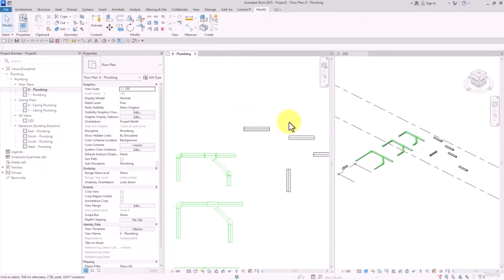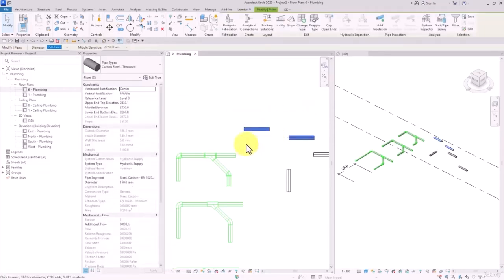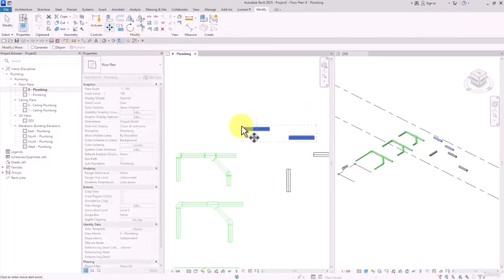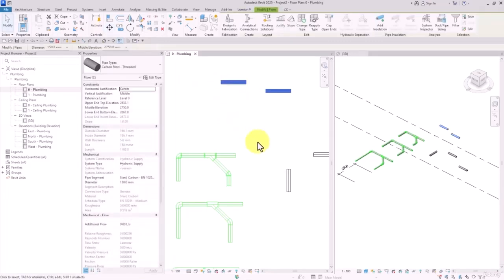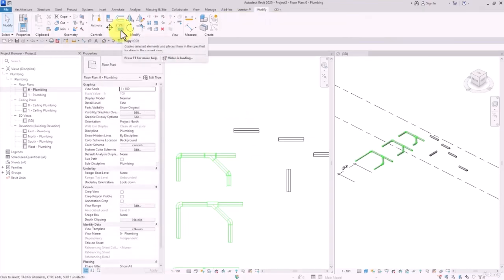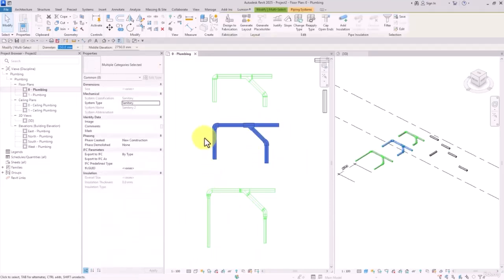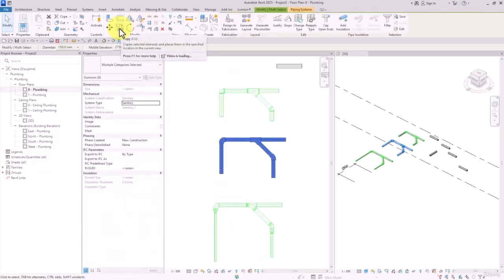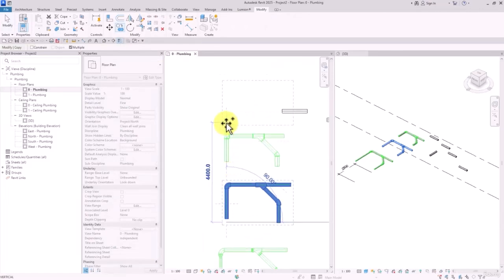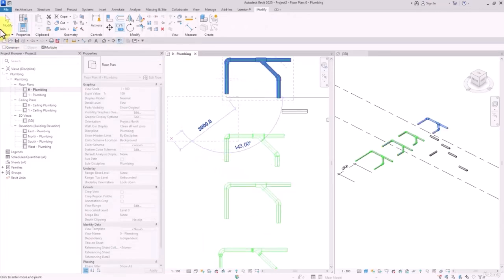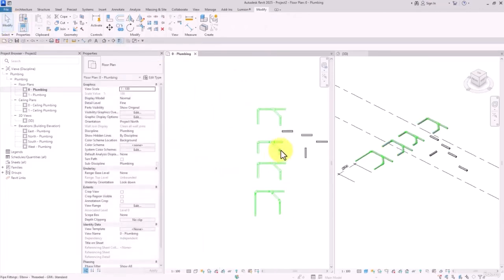The next item is Move. Well, you can actually guess what it does. You can select the objects and then use Move, then select a base point and use that base point to change the location of that object. All right, next item is Copy. Again, you need to select the objects first, then select Copy, and then create some copies of the selected objects and move them or set them wherever we want.